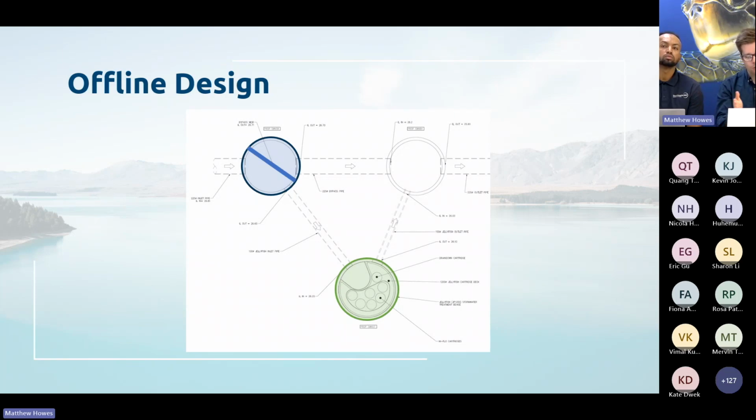So it's very important, as Johannes said, that you design that weir accordingly. All treatment devices have overflow structures within them as part of it, but it's designed as an overflow rather than a peak flow bypass. And the head losses across a diversion weir are going to be that much less because it's that much longer than a small overflow baffle structure. So that's quite important.